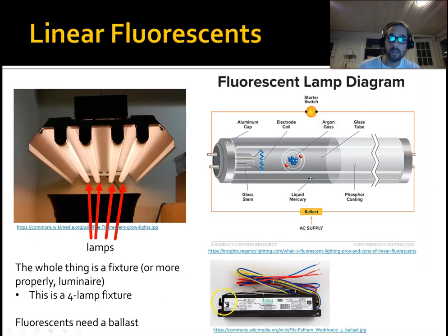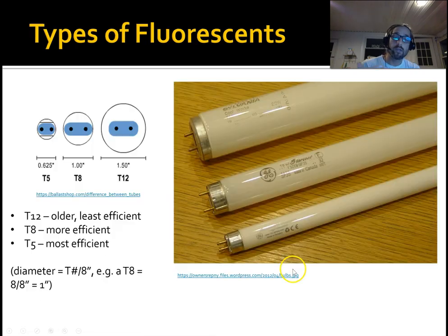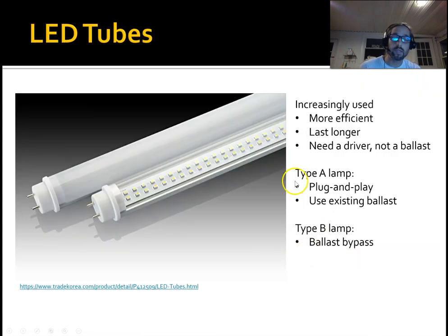Electricity is still going through there before it gets to the LED, which is totally fine, except for one really big problem. That ballast is probably going to burn out before the LED tube burns out. And so it can cause some issues if you do the plug and play. It's the easiest solution. You just pop them out, pop them in.